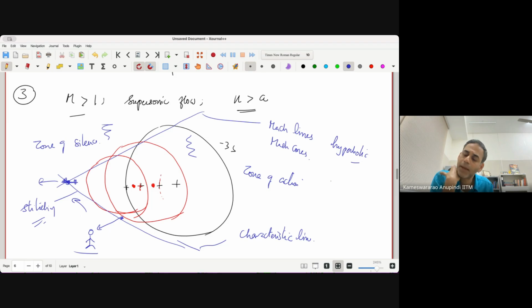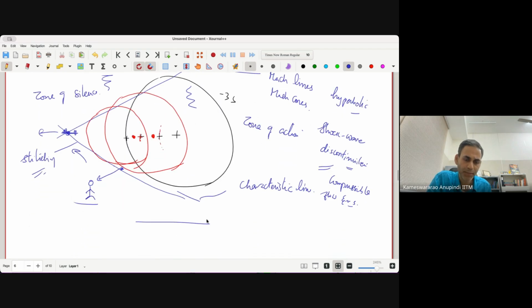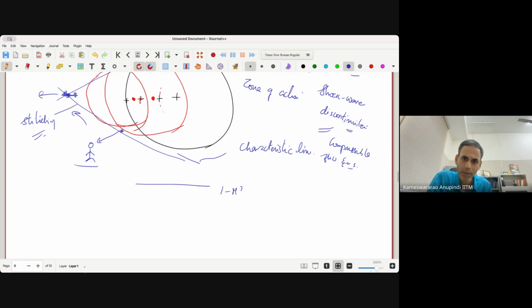And the discontinuities that we have talked about can be thought of as the shock wave discontinuities, manifesting as the discontinuities of the hyperbolic flow problems that we are trying to learn. These are usually encountered in the solution of compressible flow equations. We are not going to go too much into detail, but this single equation, 1 minus M squared times Vxx plus Vyy, nicely encapsulates all the three flow regimes and all the three types of second order PDE that we can get.